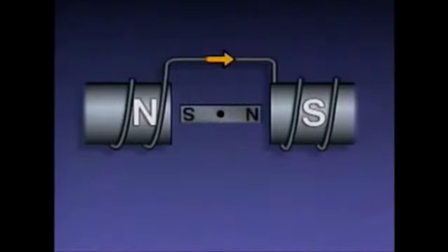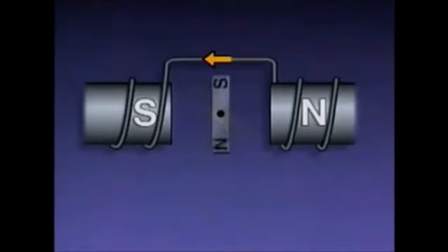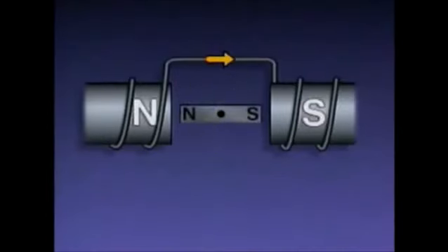As the rotor is turning, the current flow through the coils reverses direction, which causes the poles in the stator to reverse. So once again, the like poles are next to each other. The like poles repel each other, and the rotor continues to turn. As the rotor turns, the current flow reverses direction again, changing the polarities of the stator coils, and the rotor continues to turn.